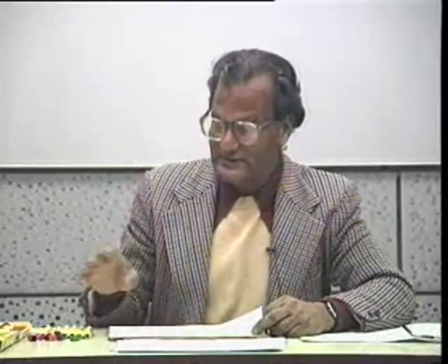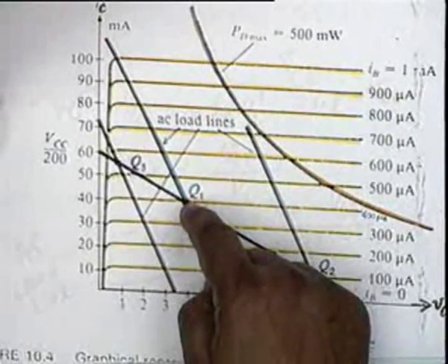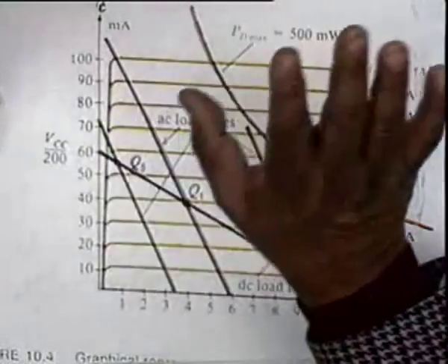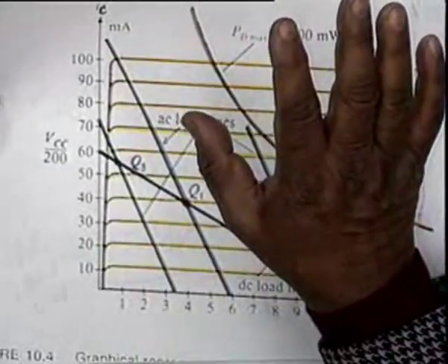We will design this circuit in such a manner that the change that happens is negligible. We have to do that. Otherwise, suppose due to a power supply fluctuation the operating point goes to Q3, then your transistor amplifier is gone. I mean, it will not be able to act as an amplifier in the context that you were using earlier.